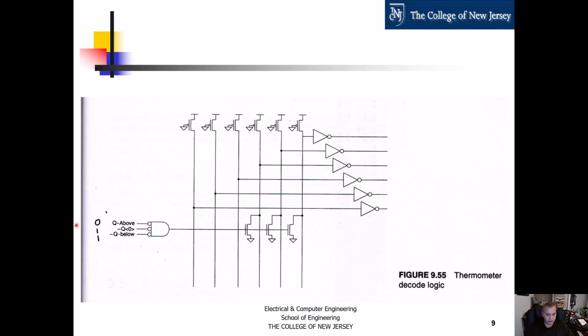Then when we go into the NOR gate, this is the NOR gate. Now if the NOR gate is 0, then these transistors are off. And this output is pulled up, which then inverts the outputs. This will get the 6 bits. This is the logic. This is the lookup table. Depending on how we program these transistors, we place them, we can get the right lookup table to get from the inputs of the 64 NOR gates the right digital value.